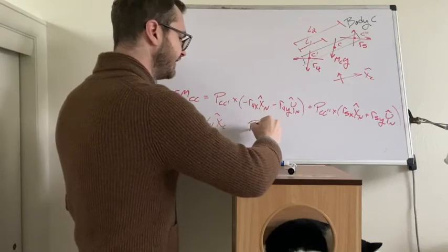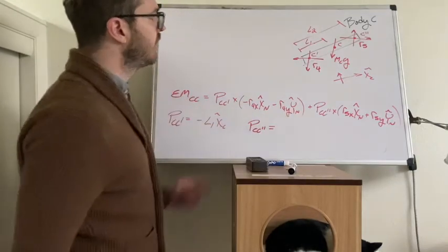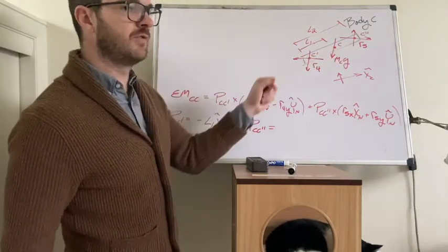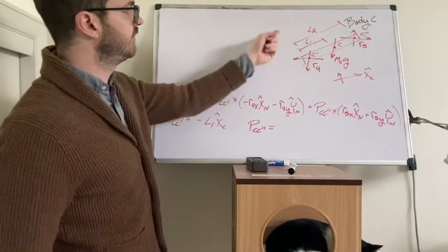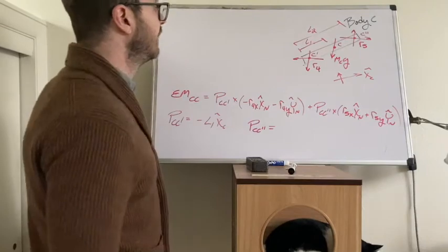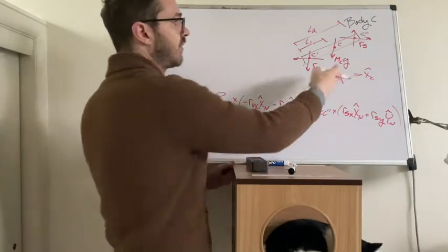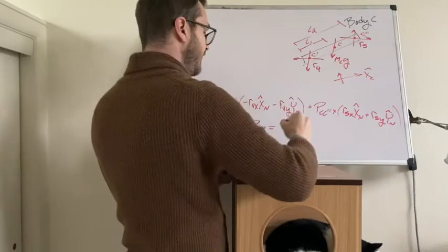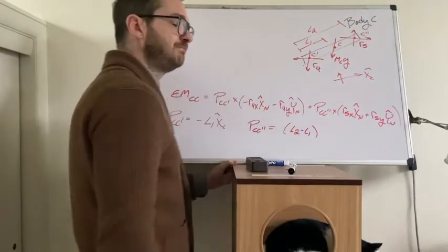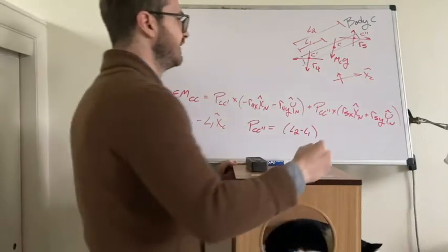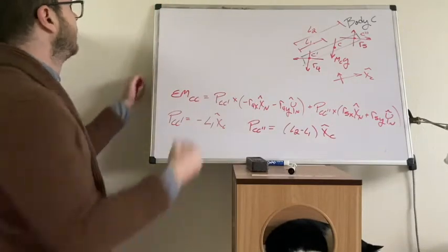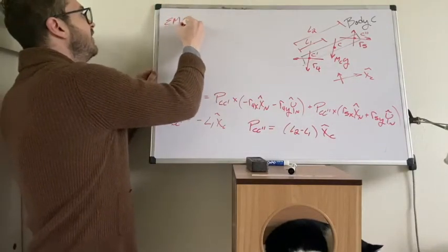And then this other position vector, C to C double prime. Remember, why is this one slightly more complicated? We are not assuming that point C was the geometric middle. This is just a slightly more generalized way of saying that the center of mass can be anywhere along this length. So if we want to go from C to C double prime, that's the center to the top right corner, that distance is going to be L2 minus L1. This is going in the XC direction. Okay. All right. So sum of moments on C about C.